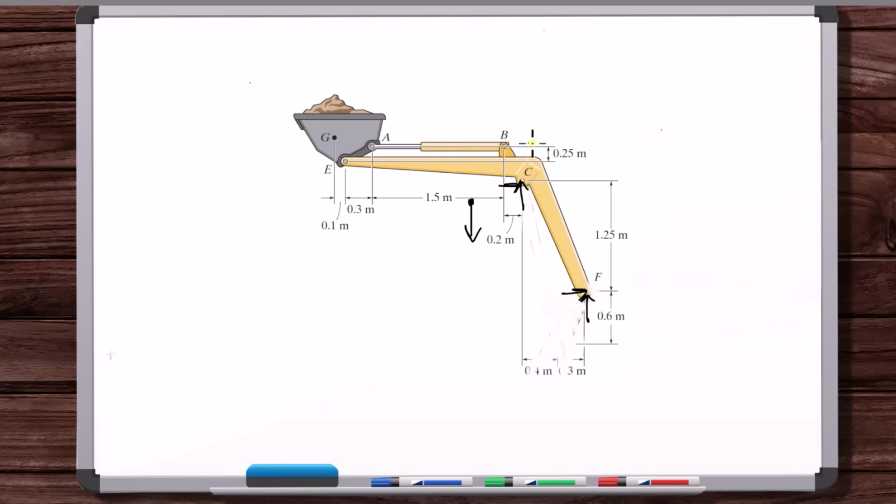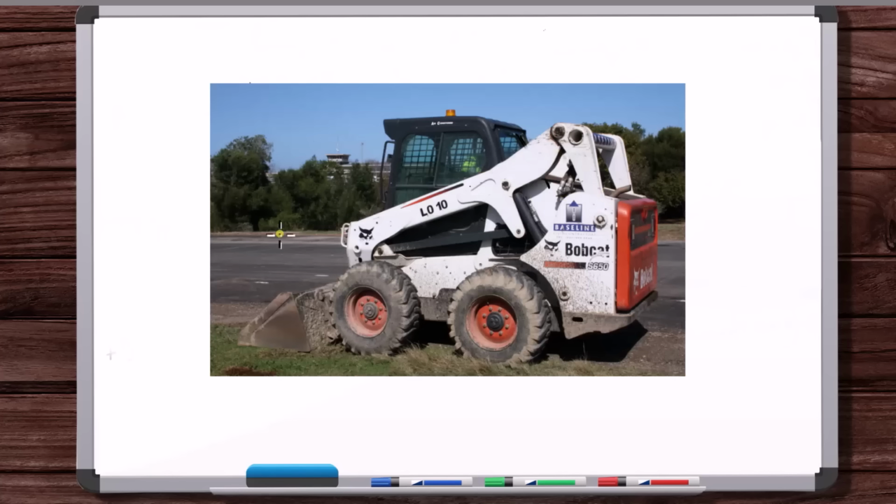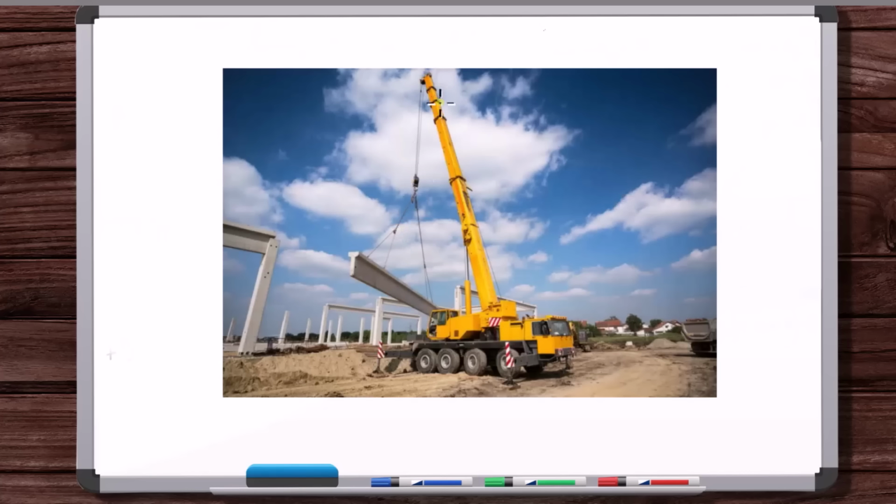Just make sure for a free body diagram you put your coordinate directions, and you have to put the dimensions too, right? So you have an entire machine, and there are all kinds of free body diagrams you could do. Mainly it's the skeleton, the structural part that you're designing to carry significant load, where you want to see if the components are going to break or not. In other words, this metal plate here is not load carrying. That's just a cover for the backside. That's probably just sheet metal, right? So you could do a free body diagram on this entire machine like it's shown here.